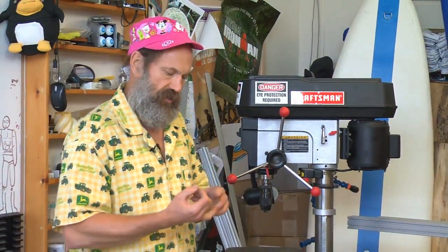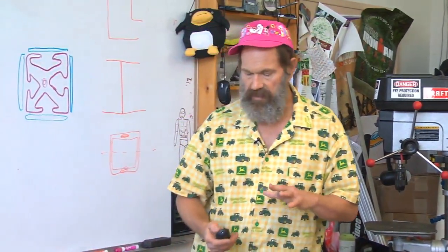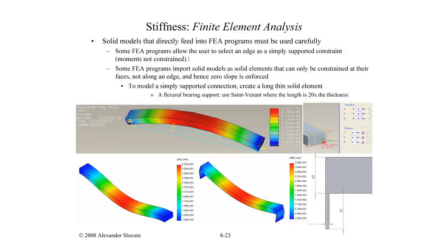So if I can write all that into one spreadsheet, I can very rapidly go through the stiffness of the gear, the strength of the gear, and play what-if with different mods very, very quickly. In the end, check with your finite element analysis just to be sure. But remember, the name of the game is to be able to move quickly through your design.